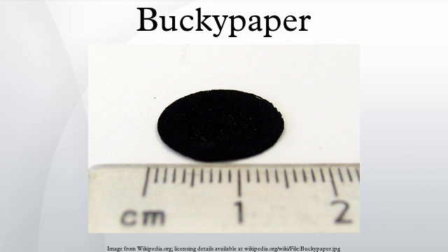Aligned multi-walled carbon nanotube growth has been used in CNT film synthesis through the domino effect. In this process, forests of MWNTs are pushed flat in a single direction, compressing their vertical orientation into the horizontal plane, which results in the formation of high-purity Buckypaper with no further purification or treatment required.